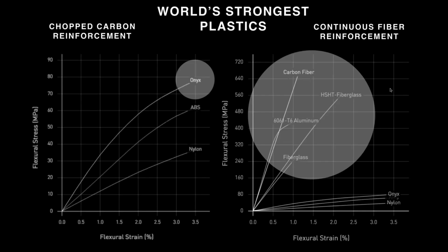So that said, this is a quick stress strain diagram showing both our base plastics and our continuous fibers. So on the left side, and by the way, is everyone seeing these stress strain curves? Yes. Great. So on the left side, I'd like to point out the base plastics that we implement. I mentioned we use a thermoplastic. So the simplest and I would say potentially most versatile base plastic we use is nylon. It's a nylon 6 blend. So that's going to have a really, really low flexural modulus, but in turn, you can get really high wear and high fatigue out of that.